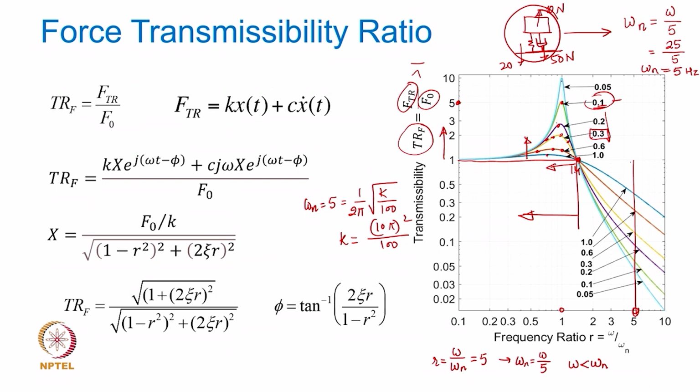It is going to be 10 pi square multiplied by 100, not divided. So much of Newton per meter, that is effective k. So, if you have 4 isolators, individual isolators will be 1/4 of that. This is roughly how the stiffness will have to be estimated for us to design the isolation system properly, so that you are operating somewhere here.